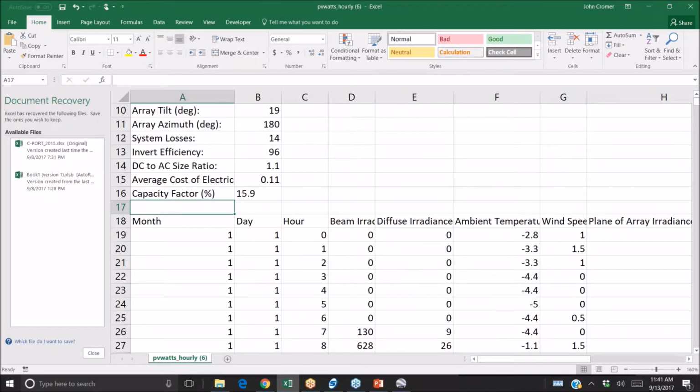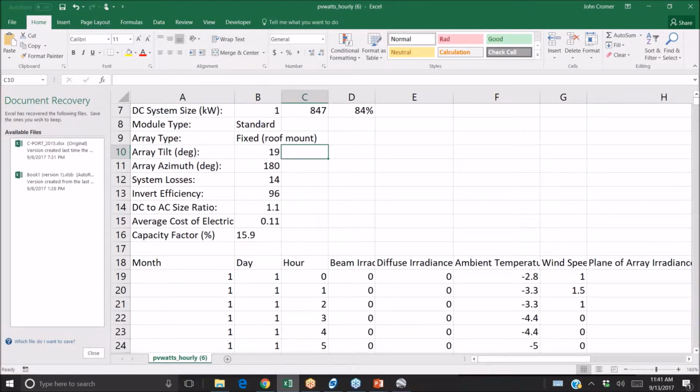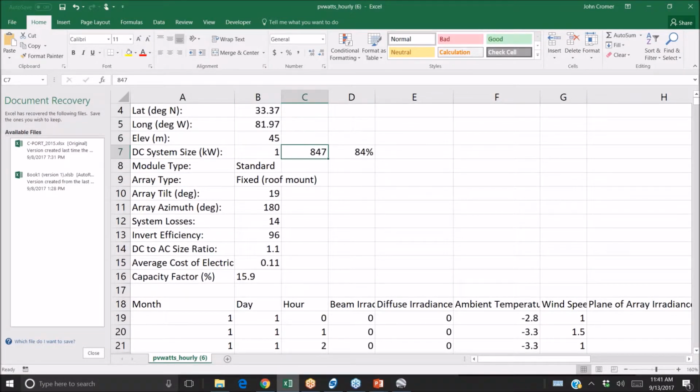And as we said before in yesterday's class, often, if your peak is 847 watts, you're generally, for most production, 99% of the production of the array is not getting above 800 watts. And so, it's very common for the solar array to be 20% or 25% oversized compared to the inverter capacity.